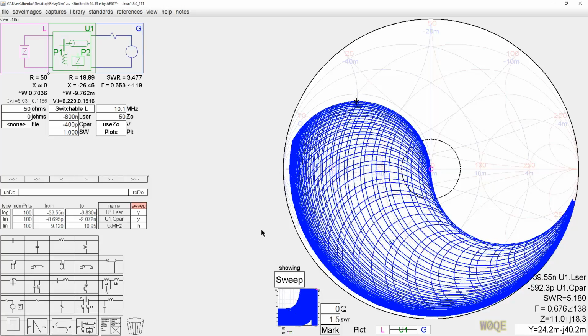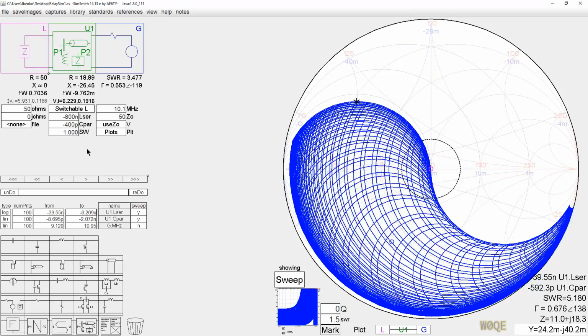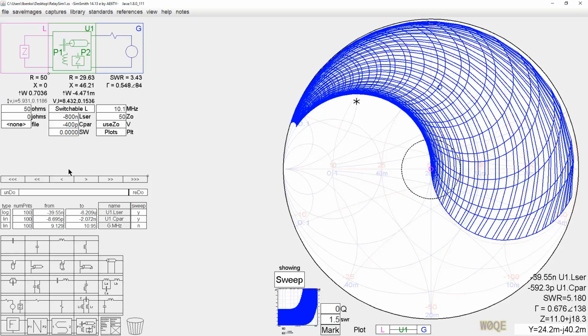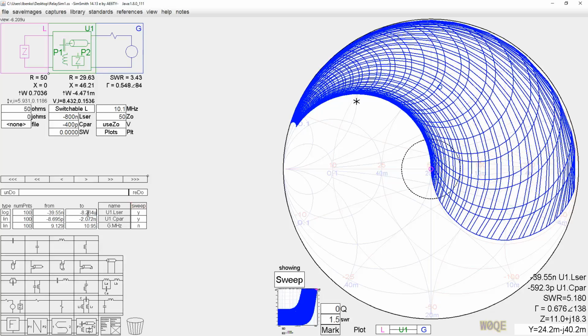All we're losing is this little tail at the end with inductance, so we don't need a 10 microhenry inductor on this side. And on this side, what happens if we have less inductance? We lose a little bit on the outside. So we do need 7 or 8 microhenries if we want to match this really well. But nevertheless, this was not a matching example.